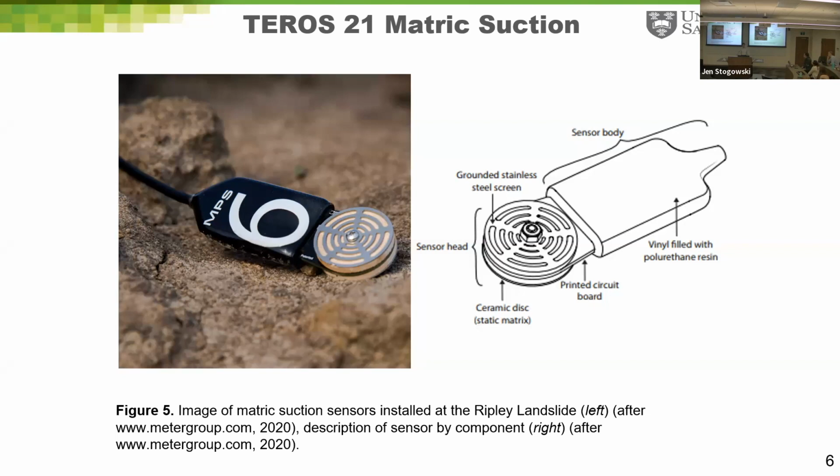They operate based on the premise of soil water potential equilibrium between the porous ceramic disc and the soil medium. The relative permittivity of the ceramic material is measured by the capacitance sensor and correlated to the ceramic's water content. The SWCC for the ceramic disc is well defined, allowing calculation of the porous stone's matric suction. Provided that the sensor is placed in good contact with the soil in the borehole, we can assume that equilibrium exists between the two, giving the soil suction.